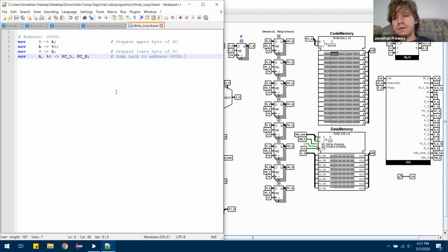And you remember the DPTR in the 8051 microcontroller? There's a program counter, and that's what's normally used for the normal address range that's in the single chip. But to use external memory, which is going to be bigger, that's probably why you want to go external, the DPTR is more bits, and so you had to do just this kind of thing. Put 2 pieces in there. Yeah, this is interesting. This is a real thing.